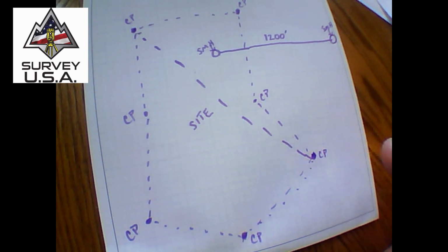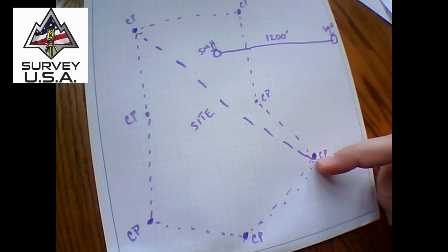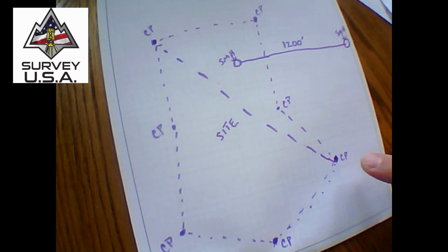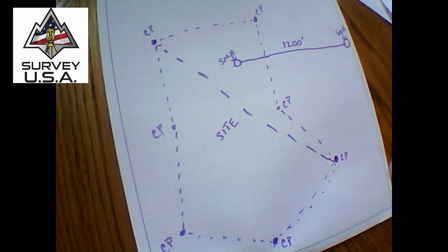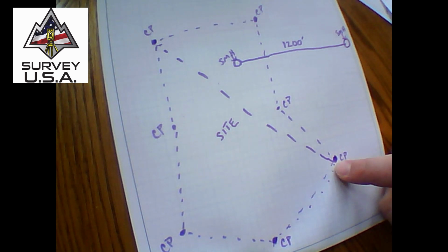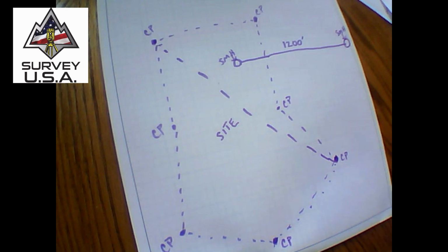If it's a small site, I've had a conversation with Dave Doyle. He's retired now, but he was the chief geodetic surveyor for NGS. I met him at a seminar. We had a discussion, and I always had this theory that the geoid basically became irrelevant. If you're on a small local site, you're spirit leveling at that point. You're saying this is this, every other point's going to be relative to it. The geoid's not going to change drastically, most likely, for a small site. This point isn't going to be, the geoid's not going to affect the difference. You're spirit leveling, calibrate to 1, go check the rest, you'll hit them, boom, your site's good to go.